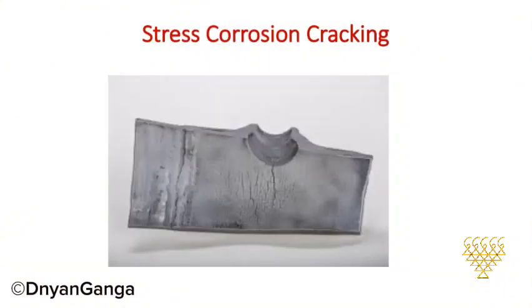Today, I want to talk about stress corrosion cracking, or SCC for short. This is a particularly insidious form of failure that occurs when a material is simultaneously exposed to tensile stress and a corrosive environment. What makes SCC so challenging is that it can happen even under very low stress levels that wouldn't normally cause cracking, especially over time. The key point to remember is that SCC involves a combination of mechanical stress and chemical attack. It's not just one or the other. This means that understanding the environment and the stress conditions is crucial for predicting and preventing it.